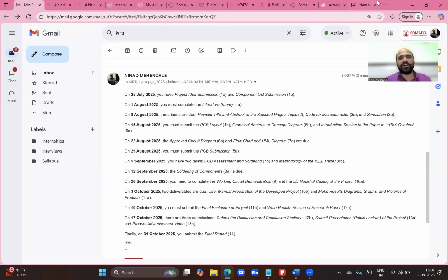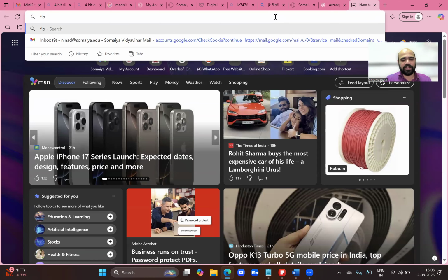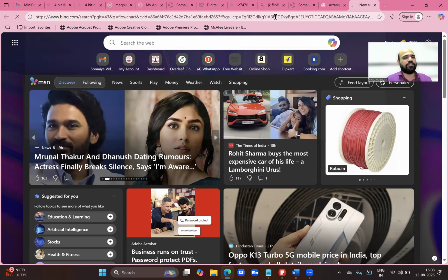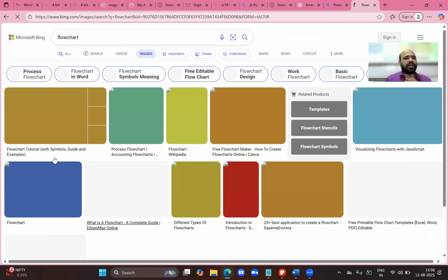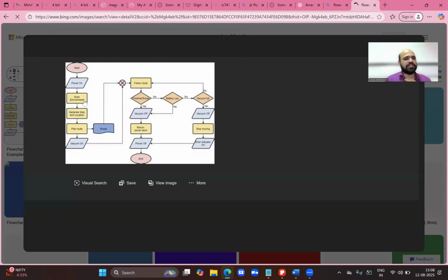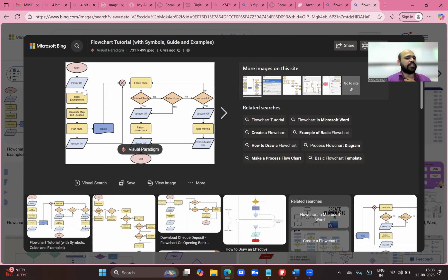If you remember flow charts in school, we have used this kind of flow chart mechanism. So this will be mostly for the software that you are going to create, and your ideal flowchart should look something like this. Okay. You have your start and then you have an end. If it is a continuous loop, which will be the case for most of the microcontroller based process, none of the arrows should reach the end and it will just keep rotating around, just like a real-time system. So that will be your next assignment.